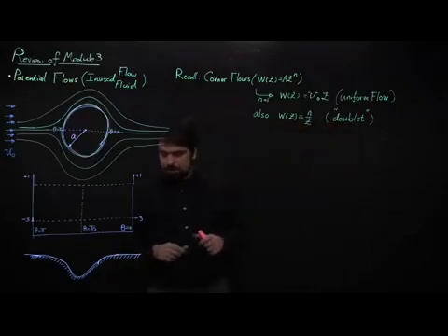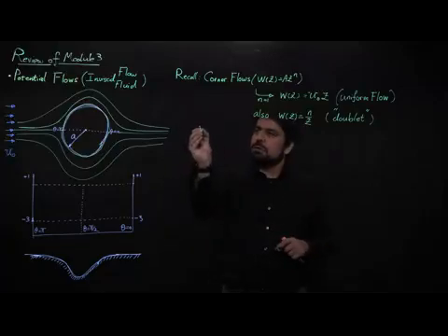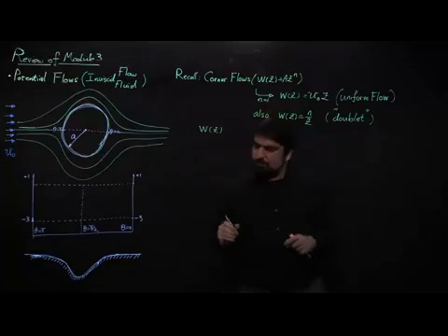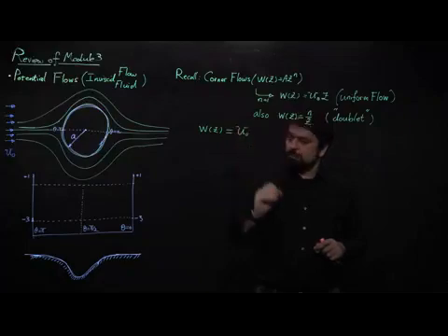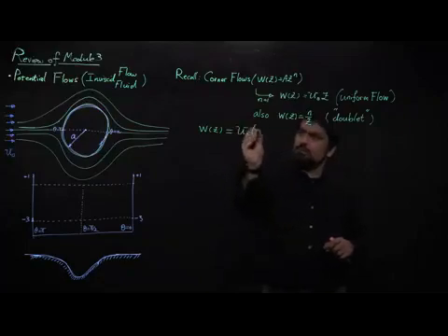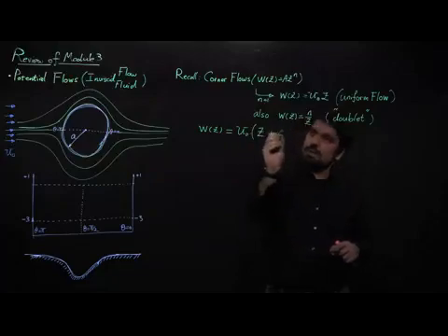And if you recall, we showed that if we combine these two together, so we construct a new W(z) which has a uniform flow part and also a doublet, and we linearly superpose these two solutions on top of each other in this manner, with U0 outside of the parentheses and inside the parentheses z plus a squared over z.